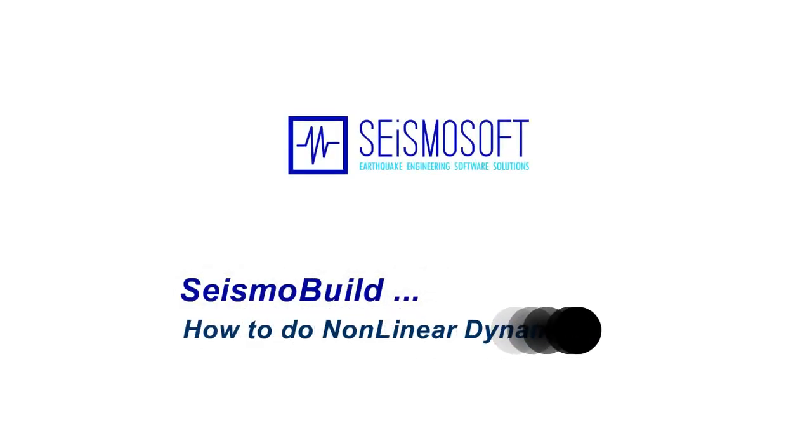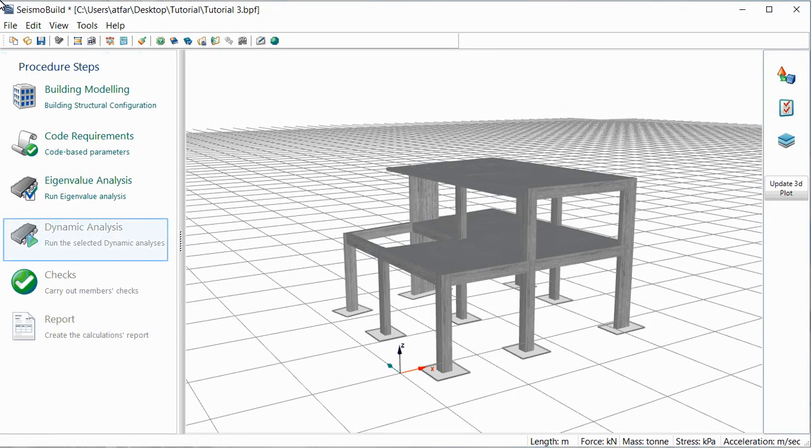This is a quick tutorial of how to do nonlinear dynamic analysis in SeismoBuild. In order to perform nonlinear dynamic analysis, we must first create our model, define the code requirements and perform the eigenvalue analysis. Therefore, we select the Code Requirements button on the Procedure step list once we have completed our model.